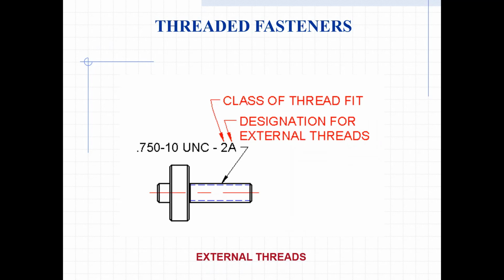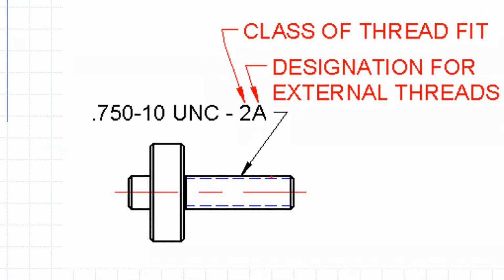Okay. So whenever I draw this, and I know this needs to be a 3/4 inch thread, what kind of diameter do you think I should make this? What should it be? Yeah, 0.75, right? Okay, 0.75. Now, whenever I put these hidden lines in, how far down should I make it go? I haven't told you this yet. I mean, it's supposed to represent the root diameter, right? Minor diameter.